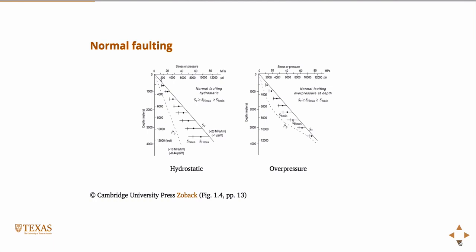The material would just float on top of water, right? So while in an overpressure scenario it can approach the vertical stress, it can never exceed it. As it approaches the vertical stress, based on the other rules we have, we can't hydraulically fracture the rock, and of course SH min is less than SH max, so it squeezes these down. Right? So this is just a qualitative look at the relationship between the stresses.